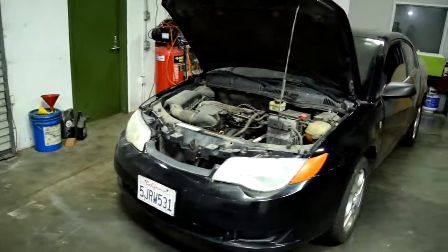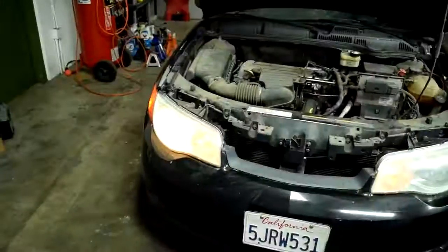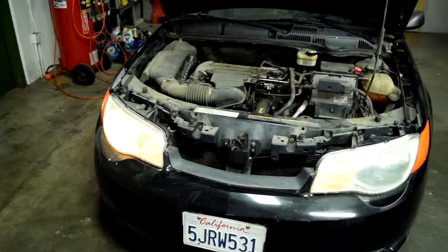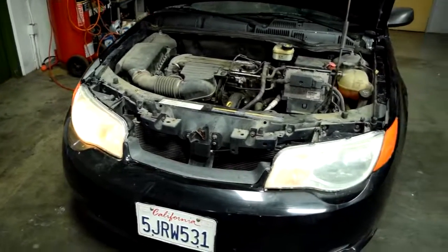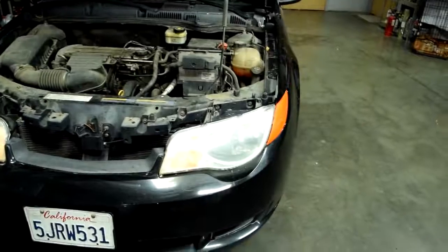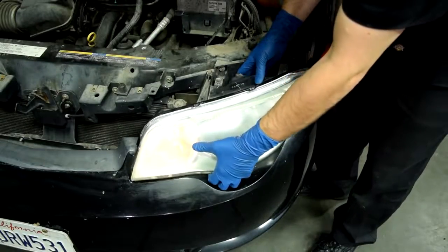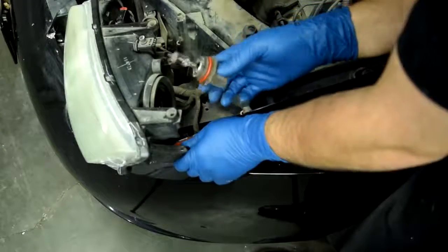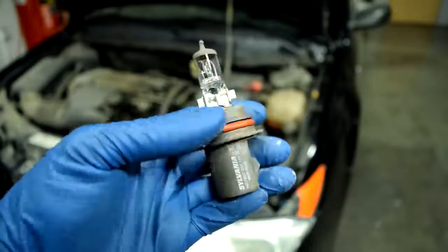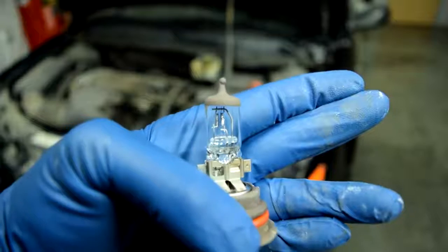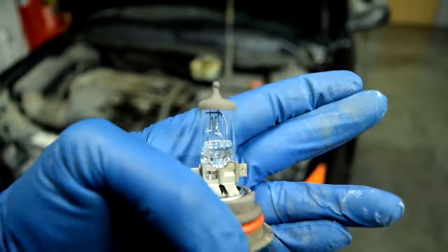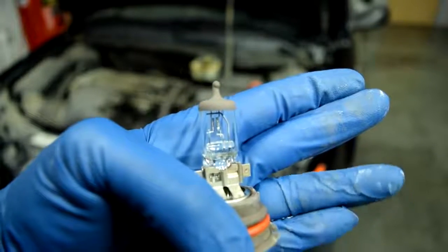Alrighty, so now let's start with diagnosing an open circuit. Alright, so the most common way that people find out they have an open circuit is that something on their car, like this driver's side headlight, stops working. So obviously the first thing they suspect is their headlight bulb, so they go to remove their headlight, remove the bulb, then take a close look at their bulb, and then take an even closer look at their bulb, and after realizing that it's not burned out, they go, oh crap.